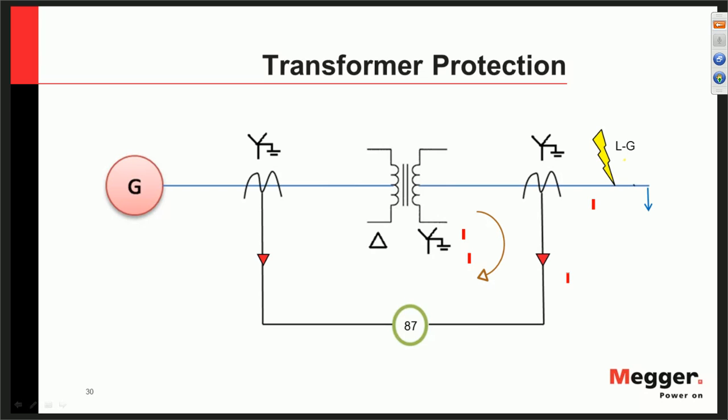We talked about the concept of zero sequence, negative sequence, and positive sequence. And I told you multiple times, remember, zero sequence is associated with line to ground faults because it's a neutral current flowing. Clearly, you can see that this network has a delta winding, and delta winding does not have a neutral here.